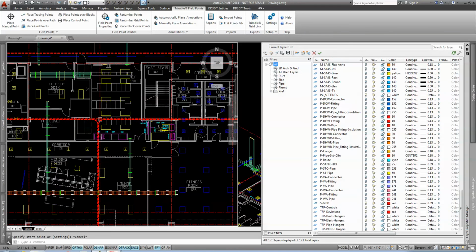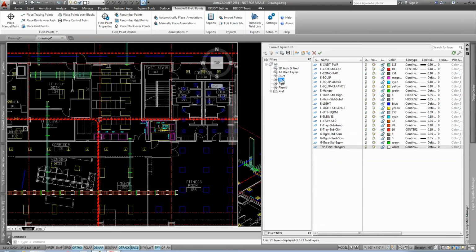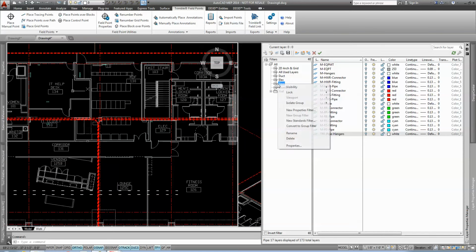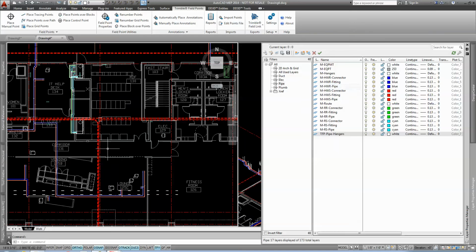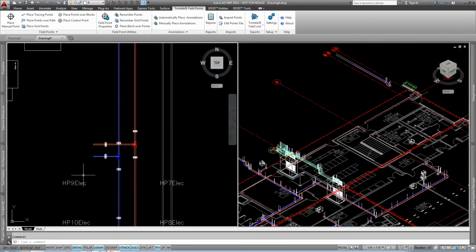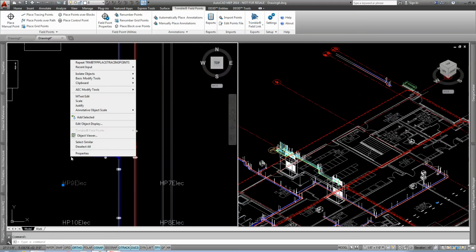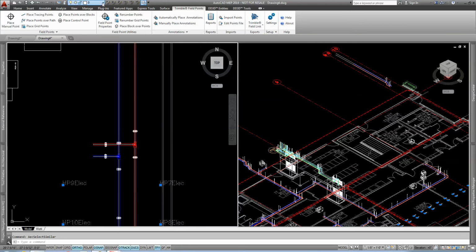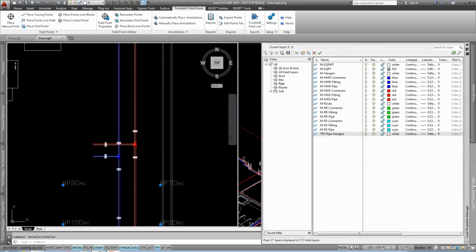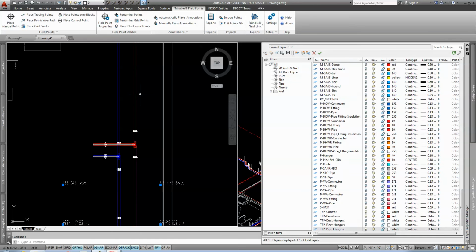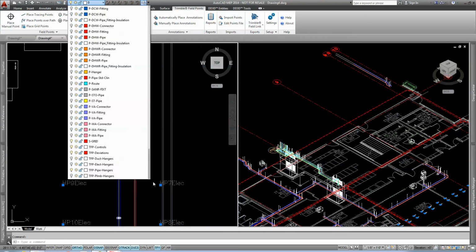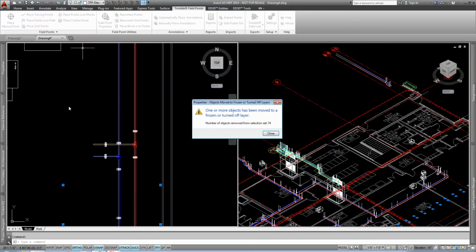Alright, so what I'm going to do now is I'm going to go ahead and turn off my electrical. Okay. Visibility off. And then I'm going to turn on my piping. Visibility on. Alright. So I'm going to have some piping right here. This was on layer 0. Do select similar. Put it back on that TFP points if I wanted to. There we go. That way it hides.